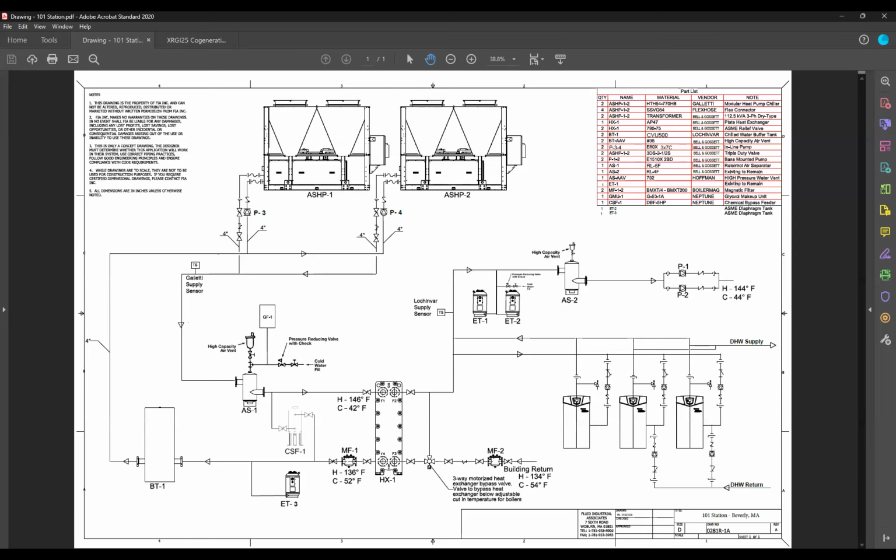That was with commercial buildings, where there's an option. I think that here in Massachusetts and anywhere that doesn't have a perfectly clean grid, it is carbon conscious to have a hybrid scenario. So in this case, this is a hybrid system where they have existing boilers. What we're doing is providing a glycol circuit and heat exchangers, circulating glycol to and from that heat exchanger and pulling off that heat exchanger. If it drops below 15 degrees, at that point, we cut off the heat pumps and kick on the boilers. And then once it's above 15, we kick it back over to the heat pumps.